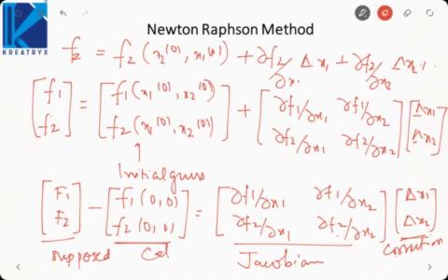Okay. So actually our aim is to determine the correction vector, and how can we determine that? By taking the inverse of the Jacobian. Okay, because initially I will assume the voltage, magnitude and the angles at each bus, and then I will modify those to arrive at the solution. So we need to know what is the modification required in each variable.